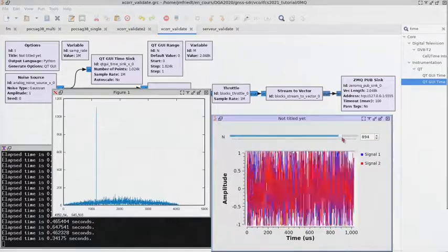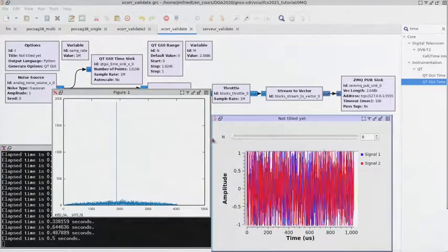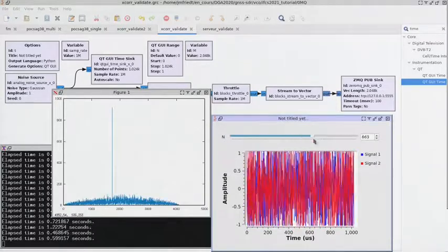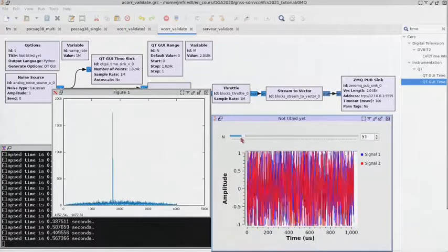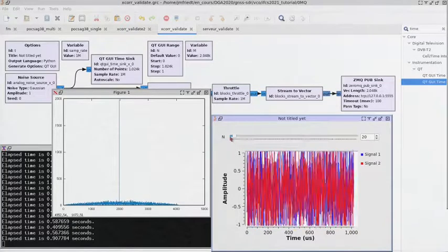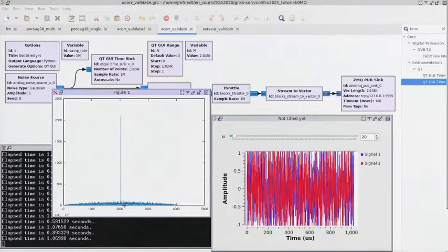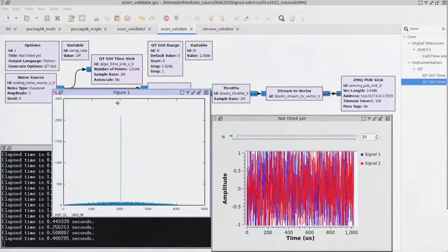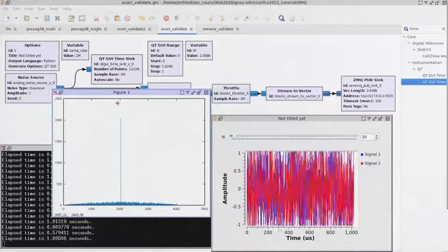By running this script, we see here that we have a correlation peak, and if we offset the time delay, we see that the correlation peak is indeed moving on the x-axis, with the x-axis providing the time delay for the reference signal to match the transmitted signal. So we see here that we can finally detect the time delay between the reference and the measurement, and the beam width is equal to one sample. This unique sample is determined by the bandwidth of the signal that is being transmitted.